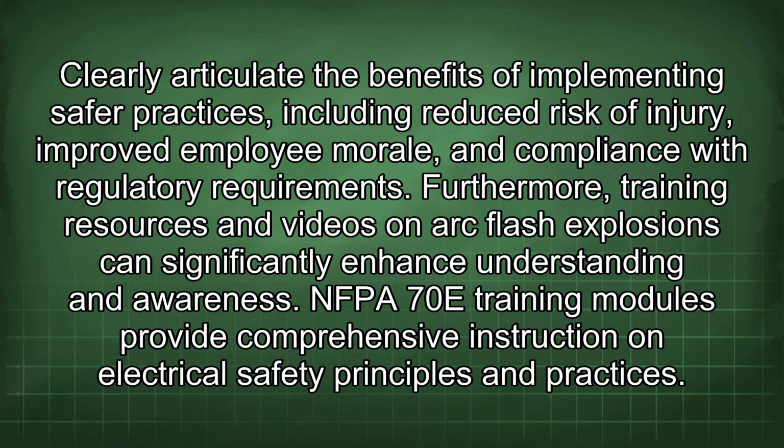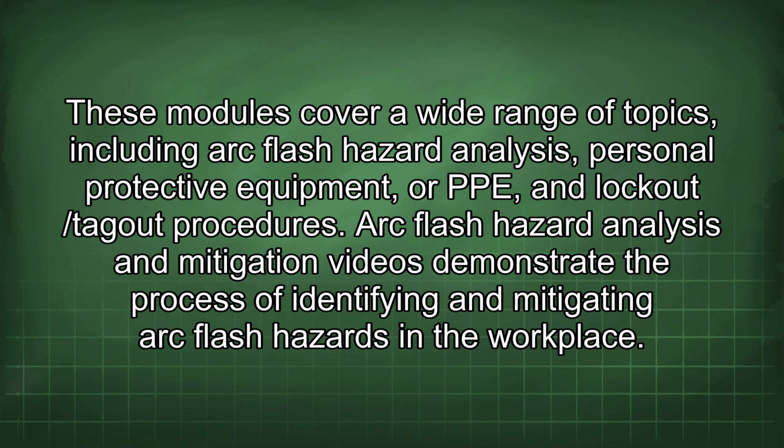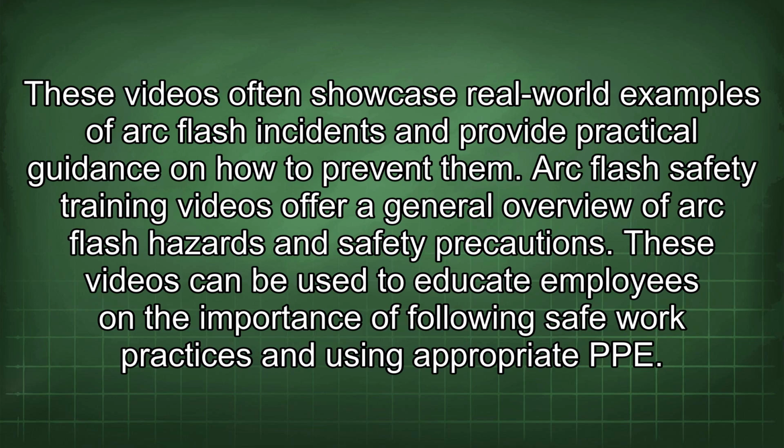Furthermore, training resources and videos on arc flash explosions can significantly enhance understanding and awareness. NFPA 70E training modules provide comprehensive instruction on electrical safety principles and practices. These modules cover a wide range of topics, including arc flash hazard analysis, personal protective equipment, or PPE, and lockout/tagout procedures. Arc flash hazard analysis and mitigation videos demonstrate the process of identifying and mitigating arc flash hazards in the workplace. These videos often showcase real-world examples of arc flash incidents and provide practical guidance on how to prevent them.